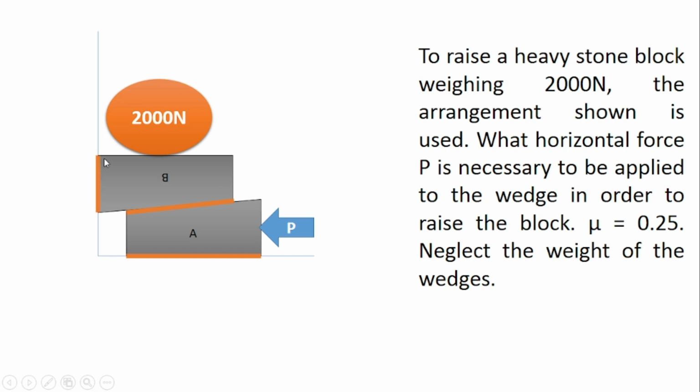So in this way we have got three areas of friction, or three surfaces of friction: friction surface 1, friction surface 2, friction surface 3. On this surface there is no friction because only weight is kept, no motion happening. On this surface no surface contact. Also on the remaining surfaces the friction does not exist because it is not in contact with any surface, or it is not in motion. So because of that we have got only 3 surfaces of friction.